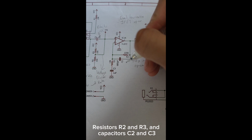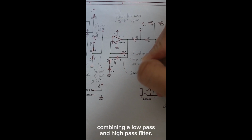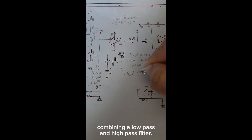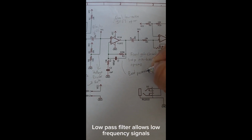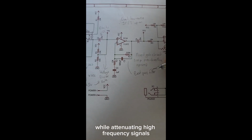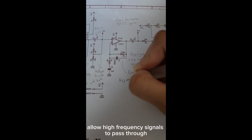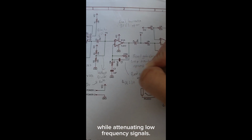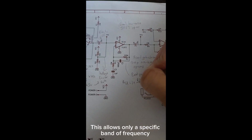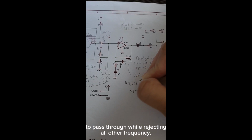Resistors R2 and R3 and capacitors C2 and C3 form the bandpass filter, combining a low-pass and high-pass filter. Low-pass filters allow low-frequency signals to pass through while attenuating high-frequency signals. On the other hand, high-pass filters allow high-frequency signals to pass through while attenuating low-frequency signals. This allows only a specific band of frequency to pass through while rejecting all other frequencies.